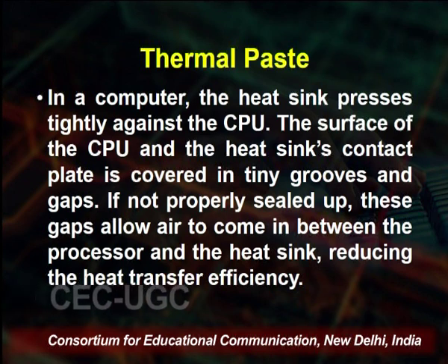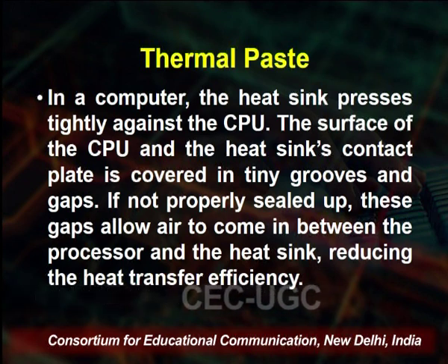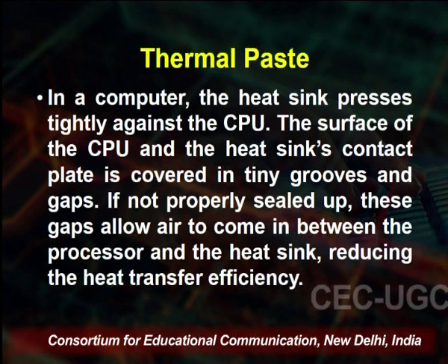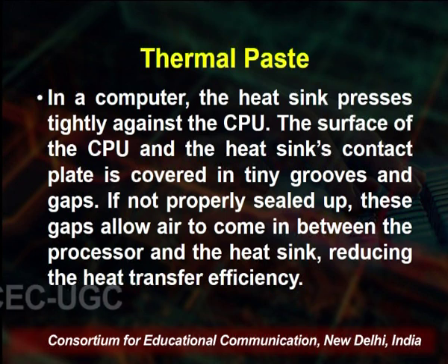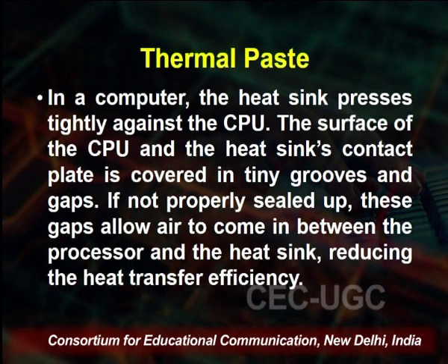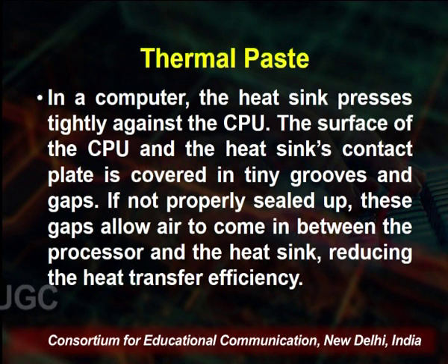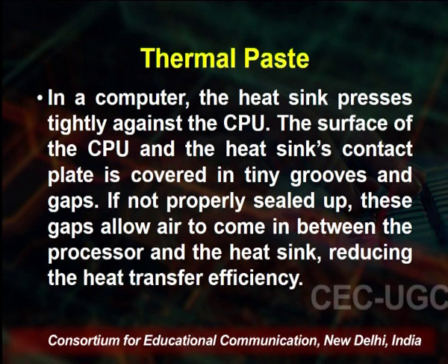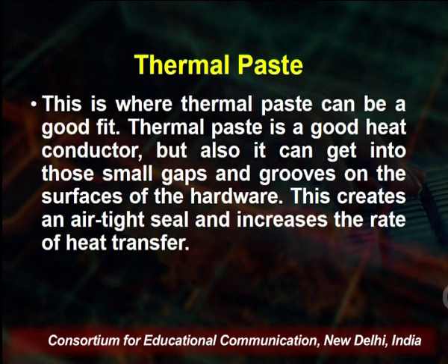In the computer, the heat sink presses tightly against the CPU. The surface of the CPU and the heat sink's contact plate is covered in tiny grooves and gaps, and it is not properly sealed up. These gaps allow air to come in between the processor and heat sink, reducing the heat transfer efficiency.